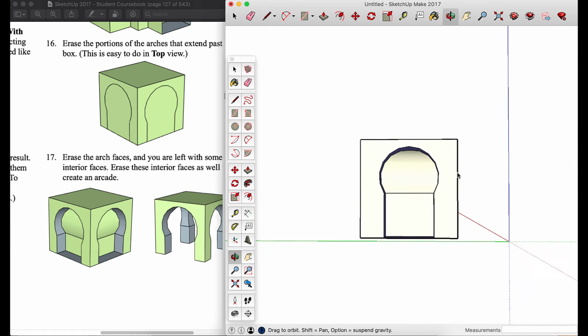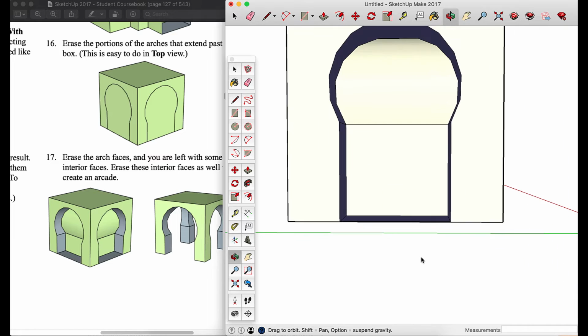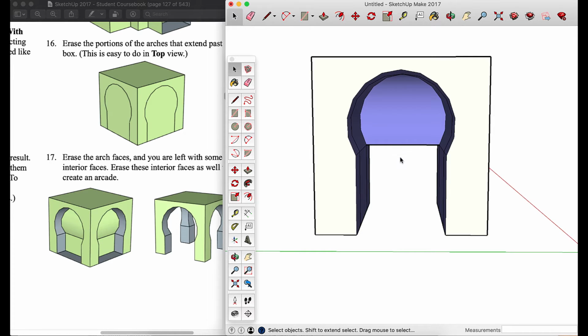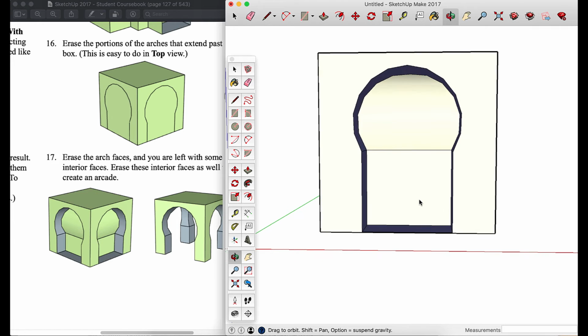Now the easiest way to do that is line up perfectly straight. Okay? Then what I want to do is I'm going to use a very, very thin right to left selection that just barely goes over that center line, and I hit delete. And I might have to do it again if it doesn't get everything through. But what's important there is you want to use very narrow and very small. Don't fill up the whole block or you'll end up getting things that are behind it.